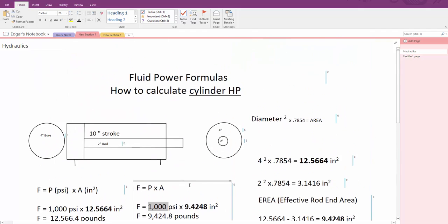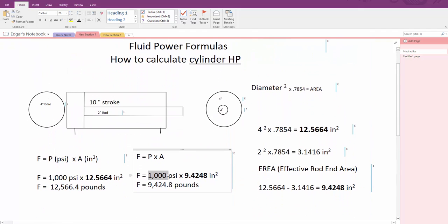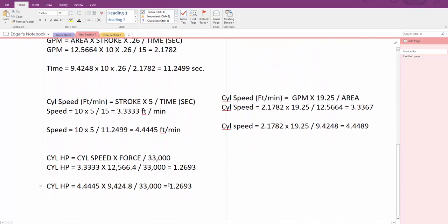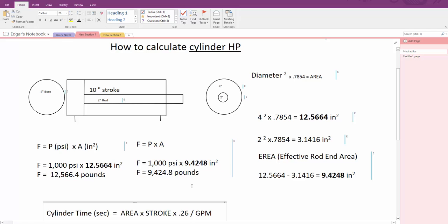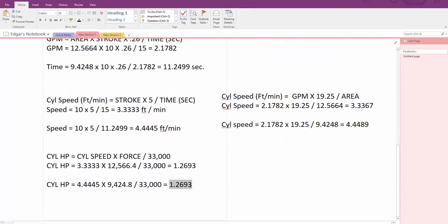Also, another thing is, in the system, you might very well have the capacity to generate that much horsepower. It is possible that the valve is set at 1000 psi and the cylinder can take 1000 psi on the retraction side, but it may not need to take 1000 psi. It may only need maybe 200 psi or very minimum pressure, and you're not going to need that much horsepower on the retraction side of the cylinder. However, the system and the cylinder are capable of producing that much horsepower, which may at one point be required in the system.